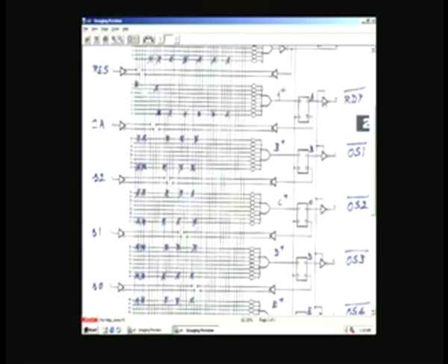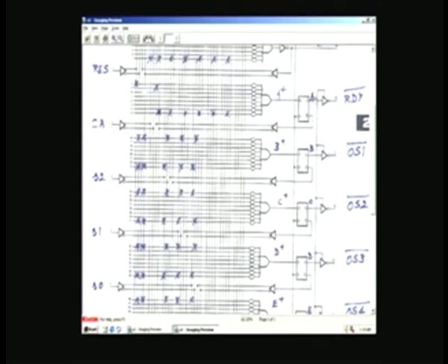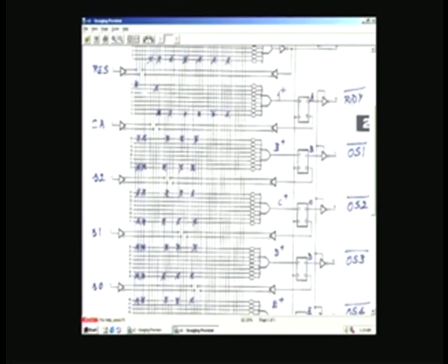Ready signal, we know that we got this from the combination logic which is in the state A. State A, B, C, D, E, F are the 6 states; five are for dispensing merchandise, candies or candy bars or soft drinks. A is the reset state, you know that. So corresponding to that we should have a ready signal. So the ready signal also comes out of this flip flop. So A, B, C, D, E, F are the 6 registered outputs. Corresponding outputs are barred, RDY bar, YS1, YS2 etc.